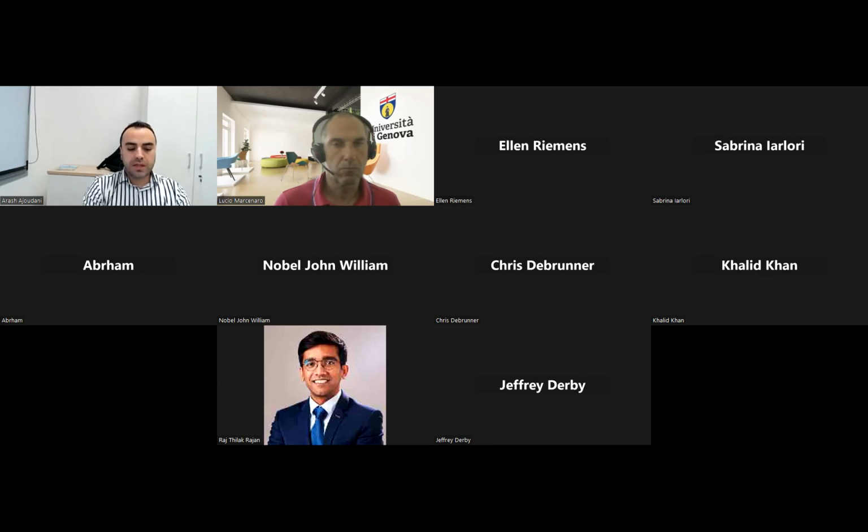So that's one. For the second question, the learning in that particular video that I showed is not reinforcement learning. We use GMMs and GMRs, basically similar to dynamic movement primitives. Reinforcement learning is something we've been recently looking into implementing, but in this case the input space is the trajectories and forces of the human demonstration, the trajectories demonstrated through an admittance interface and the forces applied by the robot.